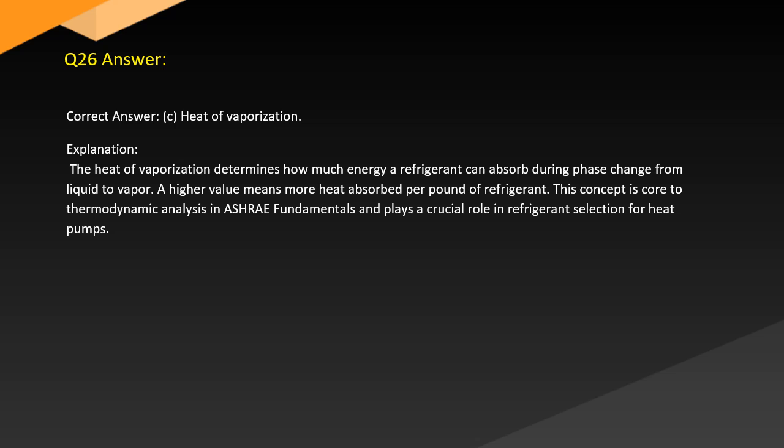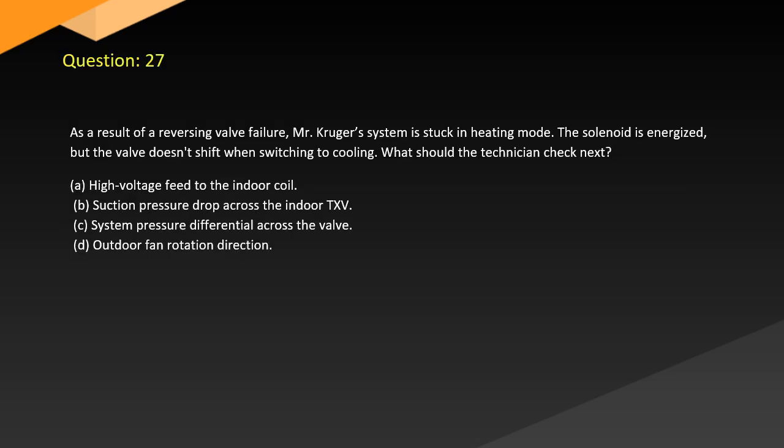Answer. Correct answer: C. Heat of vaporization. Explanation. The heat of vaporization determines how much energy a refrigerant can absorb during phase change from liquid to vapor. A higher value means more heat absorbed per pound of refrigerant. This concept is core to thermodynamic analysis in ASHRAE fundamentals and plays a crucial role in refrigerant selection for heat pumps.